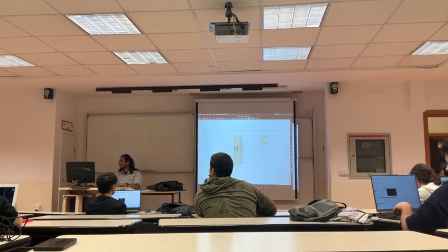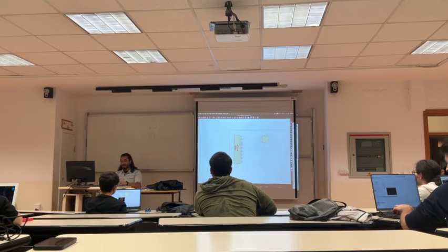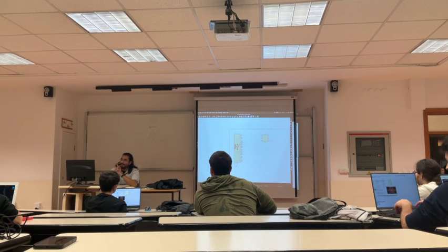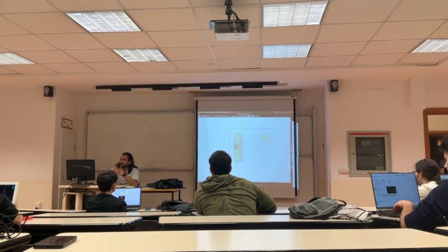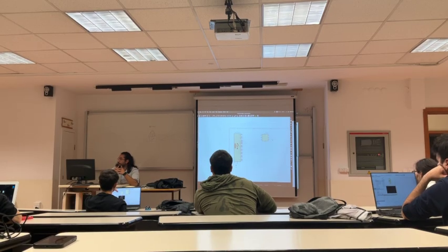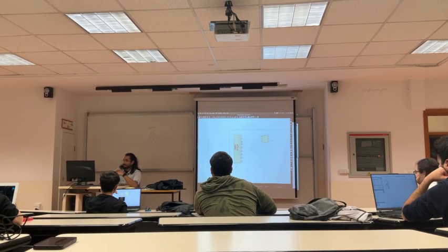It's here. You click here or you press A. Okay. You add USB Type-C receptacle and then you add NE555 and then you're done.